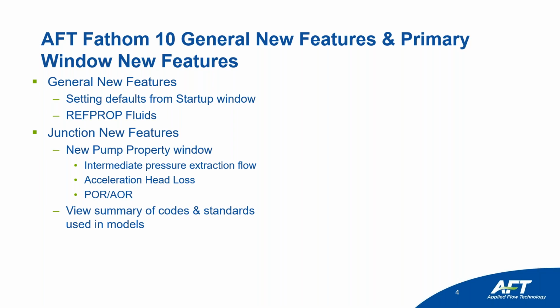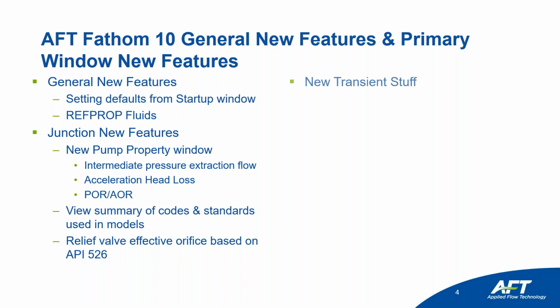So if any of you want us to be able to add in a particular standard or code that is important to you, email us and we'll work on getting that integrated as well. We've got some new capabilities with the relief valve model, and you can now select a relief valve based upon the orifice size via the API 526 standards. So I'll show you that very quickly.